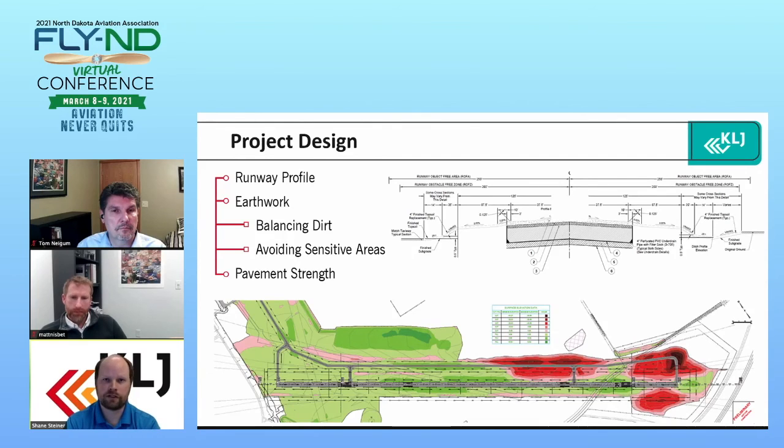We put down a layer of geogrid, and then fill in with some of the material in the cut area. So we were going to have plenty of cut area. That way, two things: it expedites the construction a little bit faster, plus gives us a little bit more uniform subgrade section throughout the whole runway, so we weren't building on one area bad, one area good, one area bad. That way it was uniform, so it should reflect and give us a good product at the end.